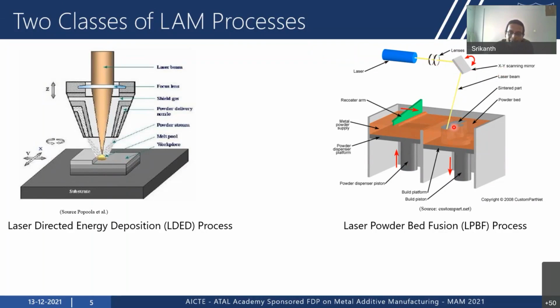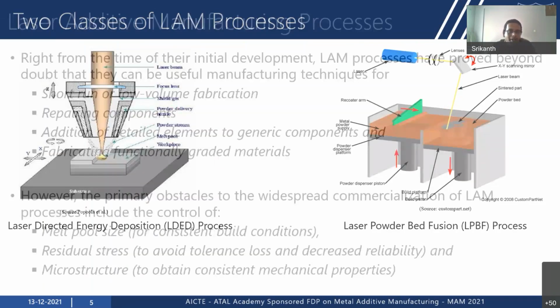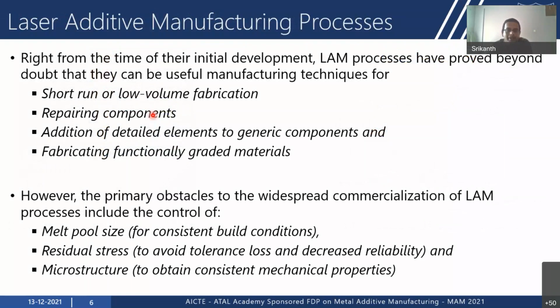Once the scanning of one layer is done, the build platform is lowered, the powder dispenser platform is raised, the next layer of powder is spread, and then the scanning takes place once again. In this way, again, you build the part line by line and layer by layer. So this is called a powder bed process, whereas LDED is referred to as a powder fed process. Particularly, this presentation will focus more on the LDED process, that is, the powder fed process.